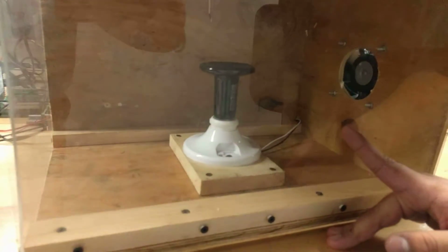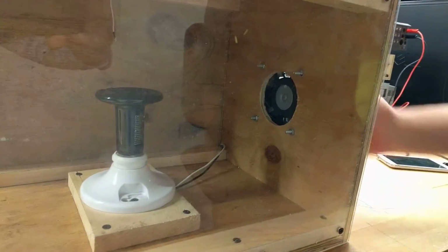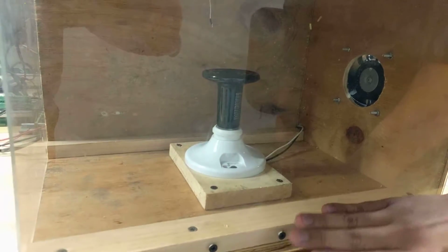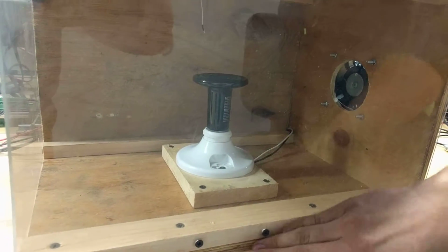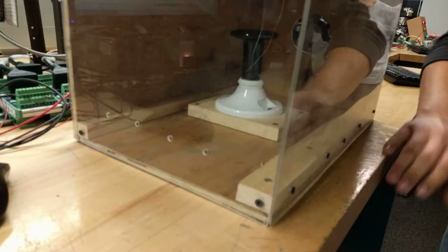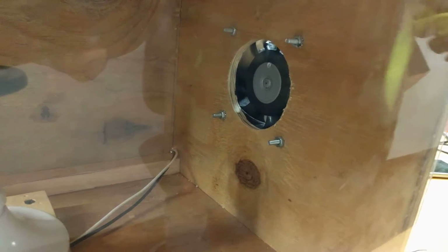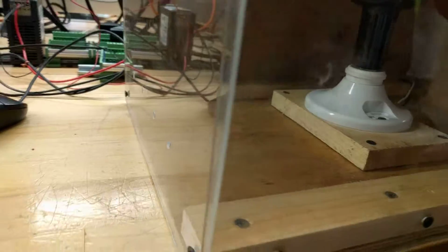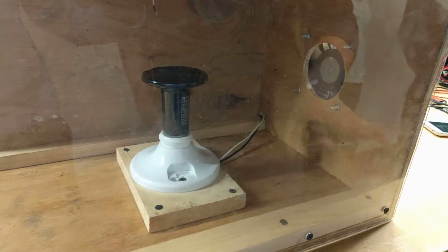Well, this is a ceramic heating element, and then we have a fan on the back. What this does is this box will heat up, and then we pull in ambient temperature air from these 4 holes over here, and then we use this fan to pull the air out. So we have hot air coming out and ambient temperature air coming in, and that's just to keep the element at a constant temperature.